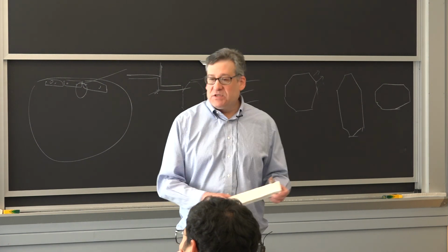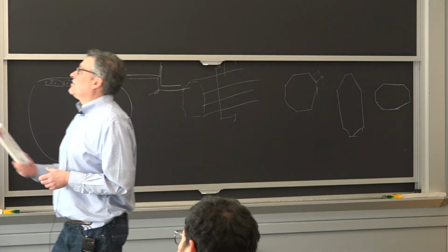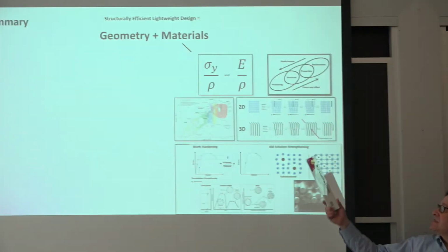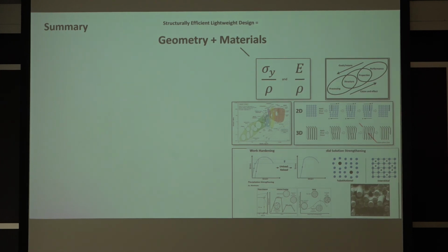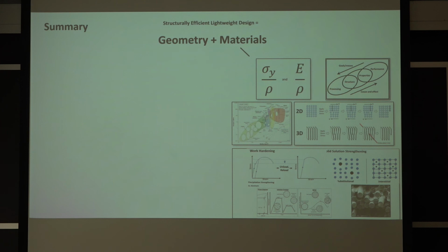So first we talked about what I just said about materials, designing materials that have these high ratios. We talked about dislocation theory, that dislocations really are the tool. There's ways we manipulate the way dislocations move through a lattice to increase strength. We design ways to manipulate how dislocations move or how they tangle up on each other. We call those strengthening mechanisms. That will give you an increase in strength to density. For an increase in stiffness, you have to go to things like using a composite, where you use a stiffer phase with maybe a less stiff phase to increase the stiffness of the overall material.